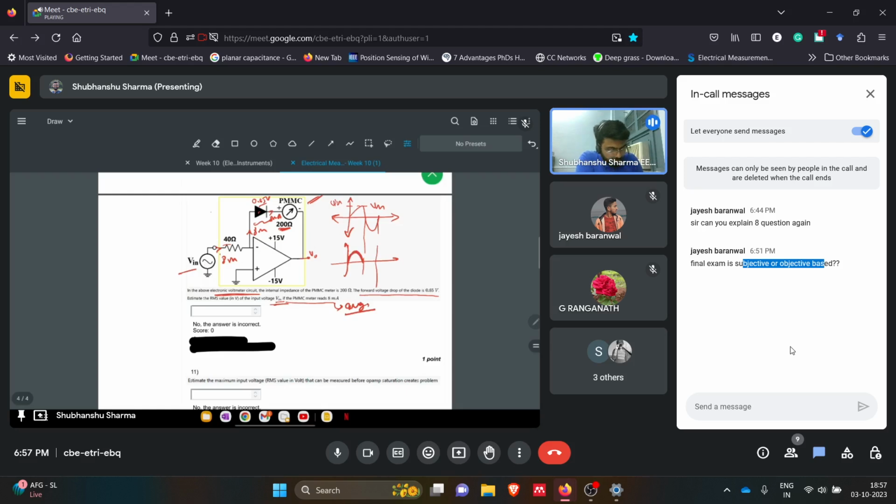But in the negative half, V will be negative, so the diode is reverse biased and we will have nothing. So what we get is a half wave rectified output. That means whatever average value we calculate will be based on the half wave sinusoidal signal. Just keep that in mind.